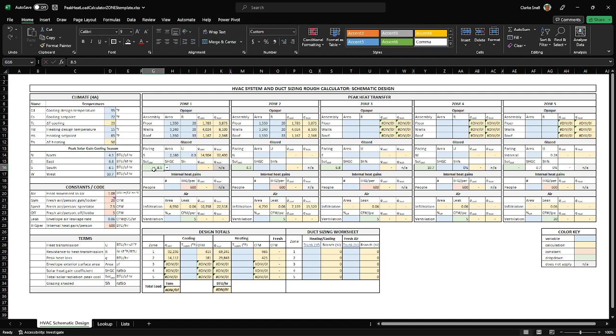Now I'm saying this is the south facing. South is 8.5, I see over here, so I'm going to choose my 8.5. I'm going to give this, let's just put in, this is above the code, but I'm going to put in 0.7. One thing I didn't mention here is glazing shading. This is simply a percentage of how much you want to shade that wall. I'm just going to put 0 in for right now. But if I changed it to 10, it's going to adjust that number.